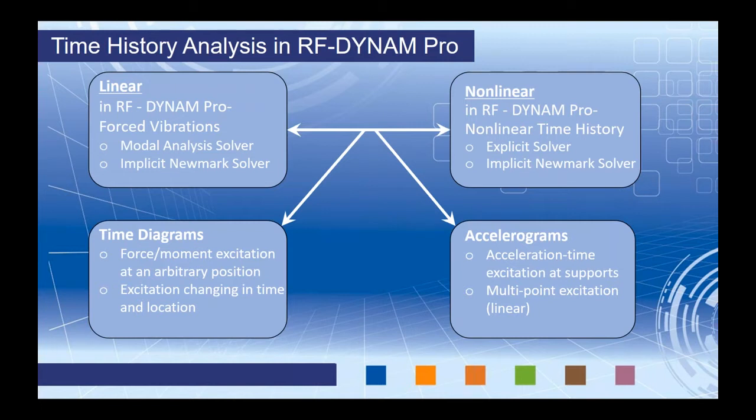Load cases define the location and the excitation of how this load will be applied according to the time diagram. So for example, we would apply loads within these load cases: nodal loads, member loads, surface loads, and many other options to determine where exactly this excitation will take place. The combination of several independent excitations is possible, and the excitation can also vary over time and position.